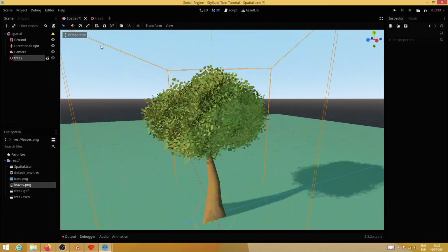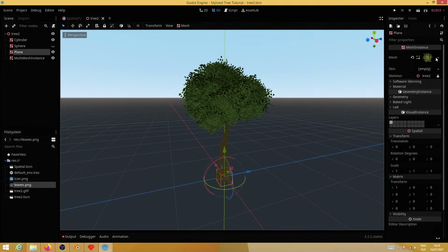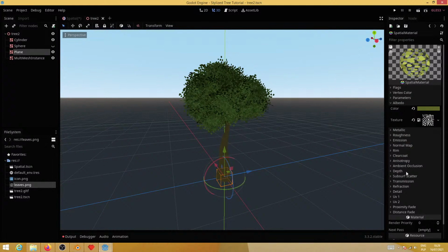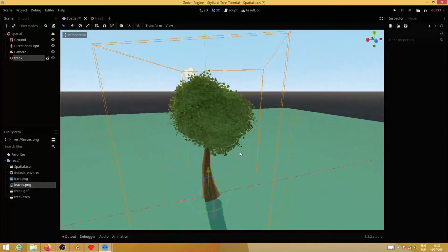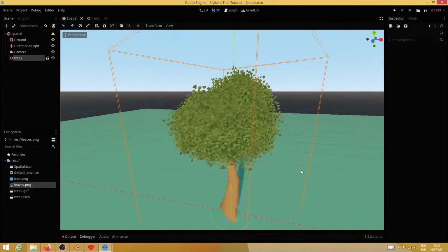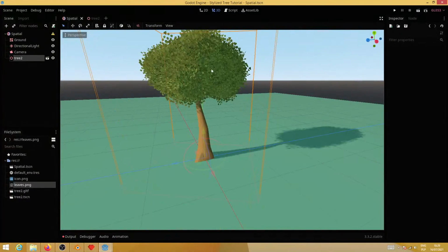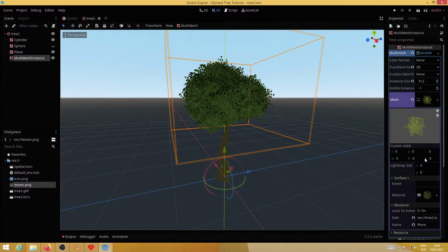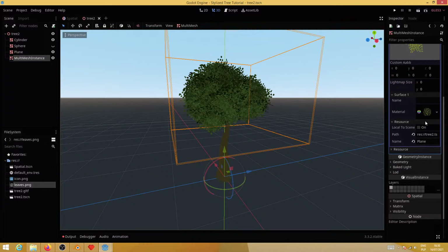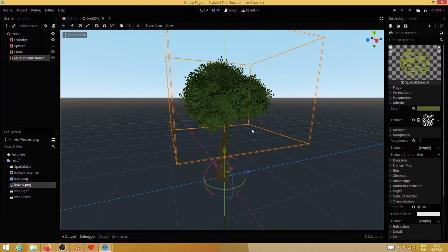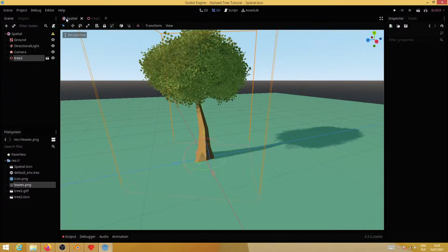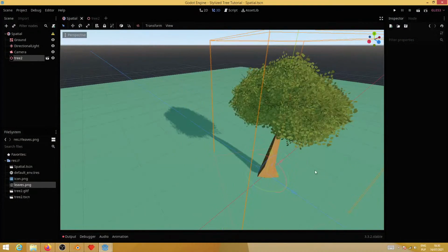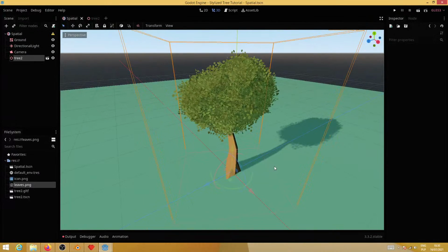And it looks slightly different compared to what we had. Mesh here, and let's turn transmission on, let's do it like that and save. And yeah, that's basically how you create it. I know what I didn't do. I didn't set up the roughness. That's why it doesn't look exactly right. Roughness 0, and here as well, roughness 0. So now it doesn't look very different, but it would sometimes.